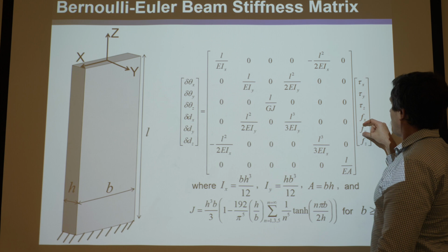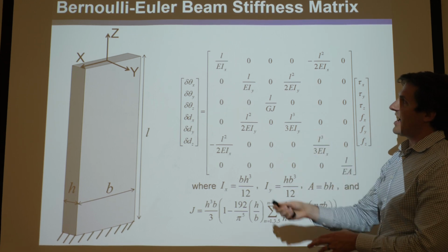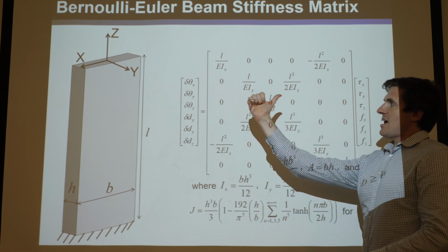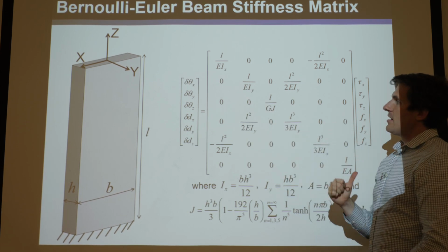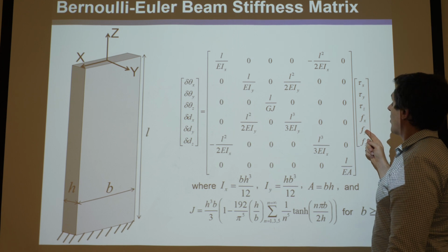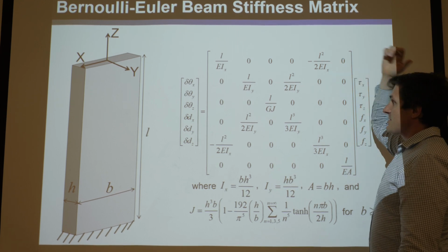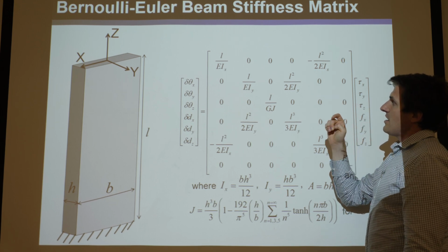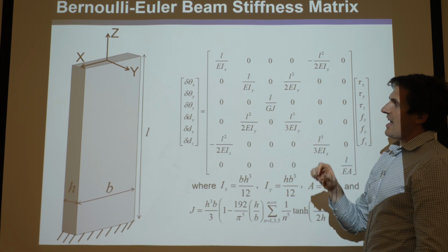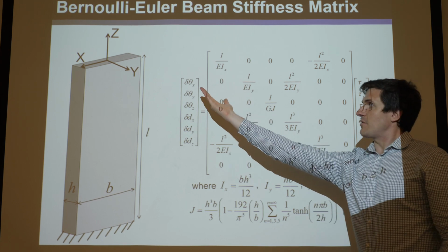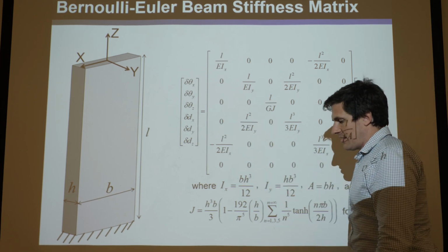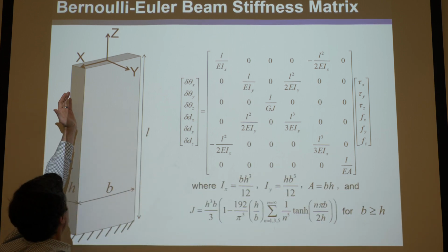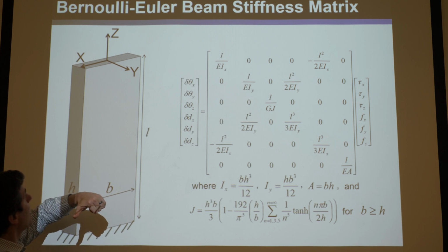And would that be true? Think about it. If Fy was positive, say I put a load up there and I pulled it in that direction, Fy positive, with a force, and I multiply it by the equation that relates that, the bending equation, you would get a theta x component. Of course, it would bend that way, right? This beam would, if you put a positive F on that, the beam would bend that way.